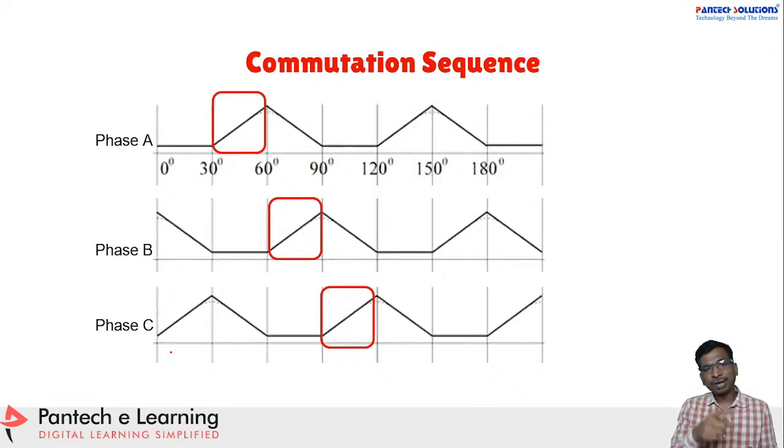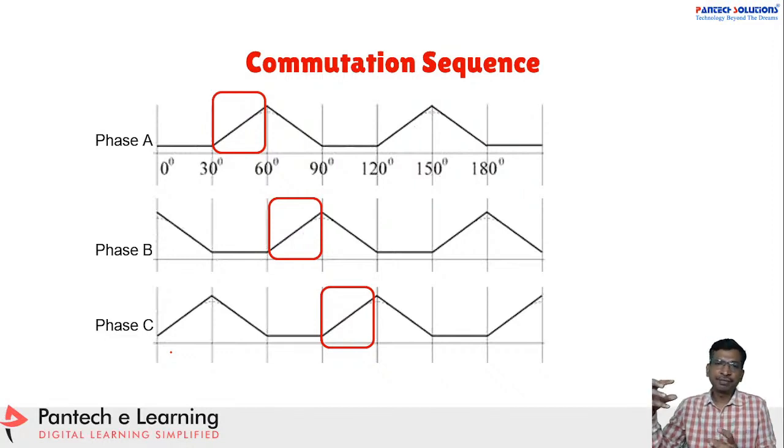If you repeat the process, then the rotor will get continuous 360-degree rotation. If the switching frequency is high, then based on the switching frequency the rotor will get aligned. So here also the motor will rotate based on the supply switching frequency, right? Is it clear?